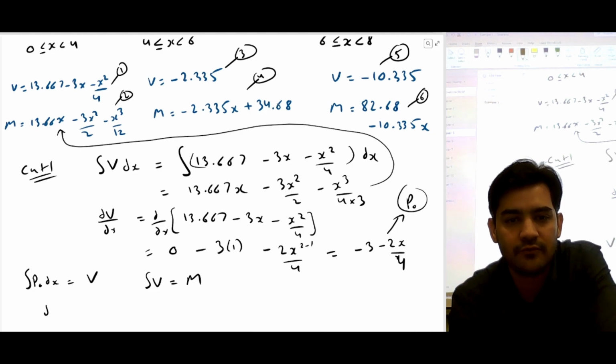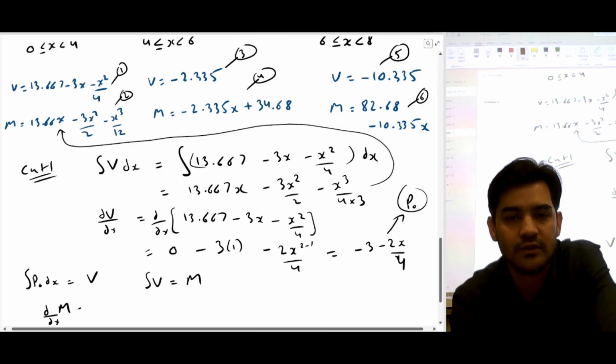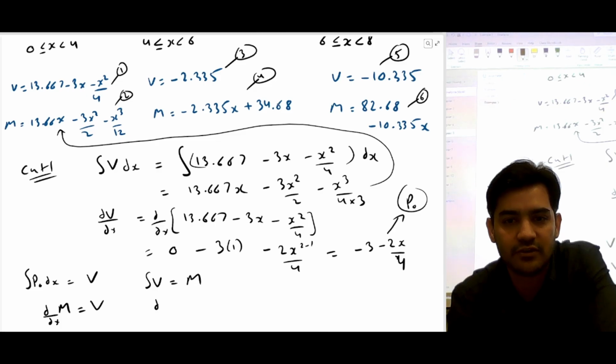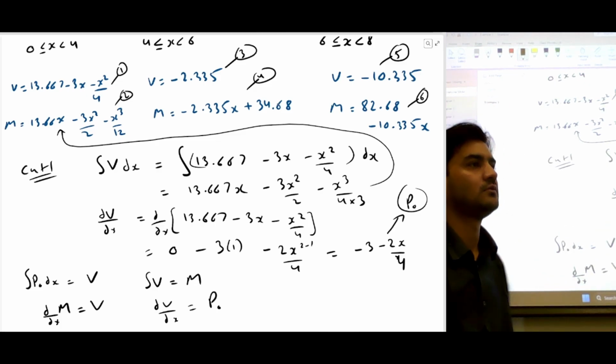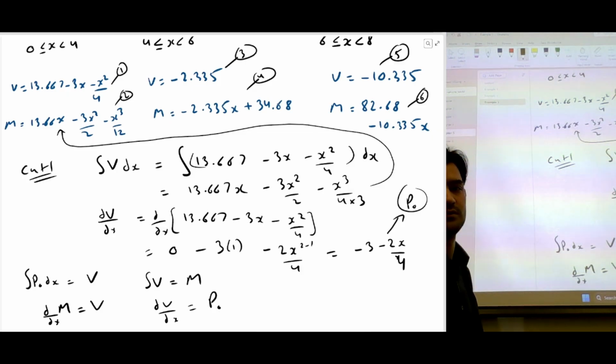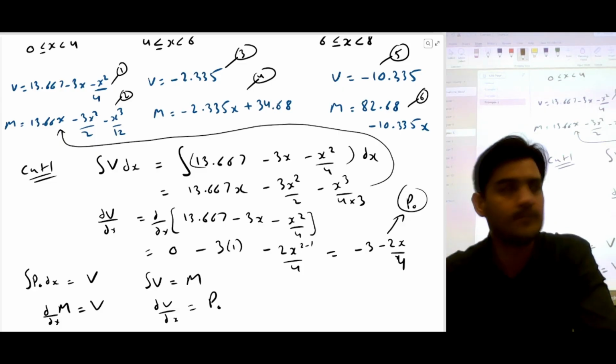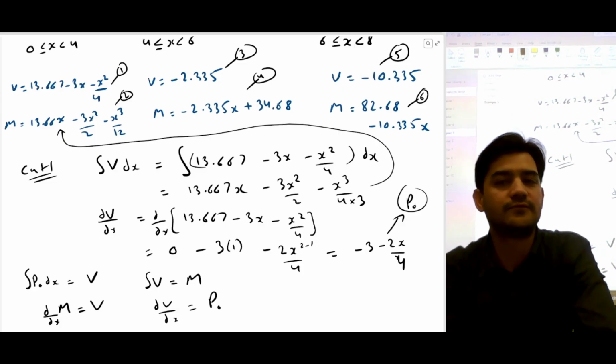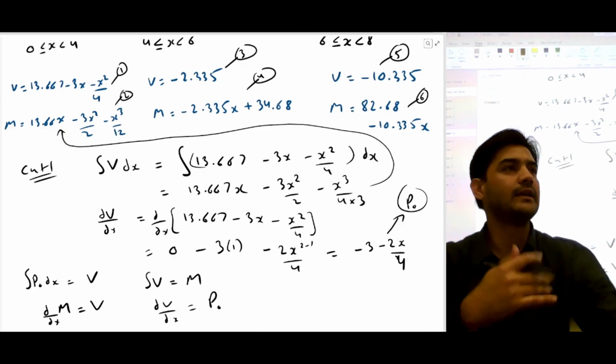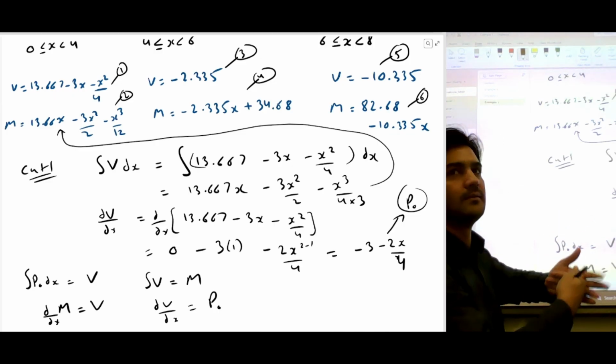And similarly, if you do the differentiation of moment, you're going to get shear force. And if you do the differentiation of shear force, you're going to get the load. This is just for your understanding, that there are relationships between the shear force, the bending moment and the load.